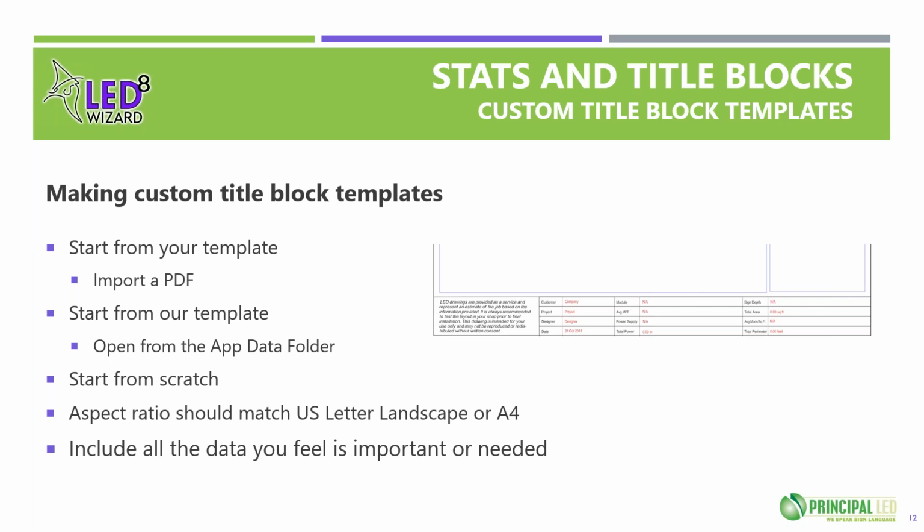As I mentioned, if you create a layout and you merge it with a title block template, you can export that. You can take that same layout, change the title block, and merge it again and export a different PDF. And now you've taken the same file, the same layout, which hasn't changed, and you've created two different PDFs and exported two different PDFs out of the same file. And that's a pretty legit way to do it.